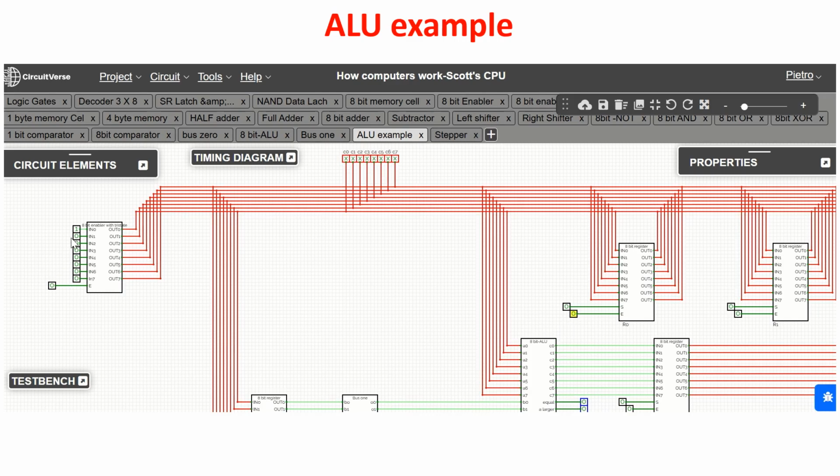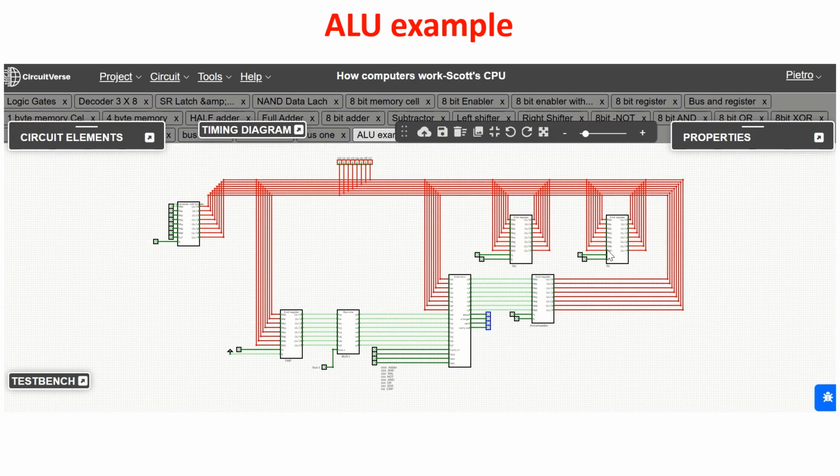Now the number 3. We put the number 3 on the bus and we acquire it in R1. So R1 acquires number 3 with the set input. Now the byte is acquired inside the register R1 and we free the bus. Let's see if the number 3 is inside the register R1, and yes. Now we want to add the content of these two registers.